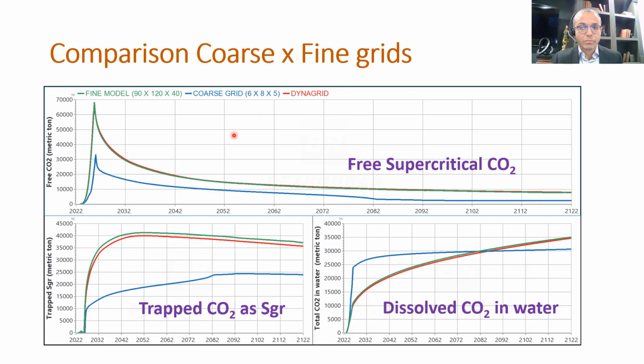Those graphs show how a coarse grid is not adequate to simulate the CO2 trapping process in porous media, which misrepresents the unstable flow and channeling. It is observed that the larger pore volume in those grid blocks amplifies the CO2 solubility. We can see this in this graph.